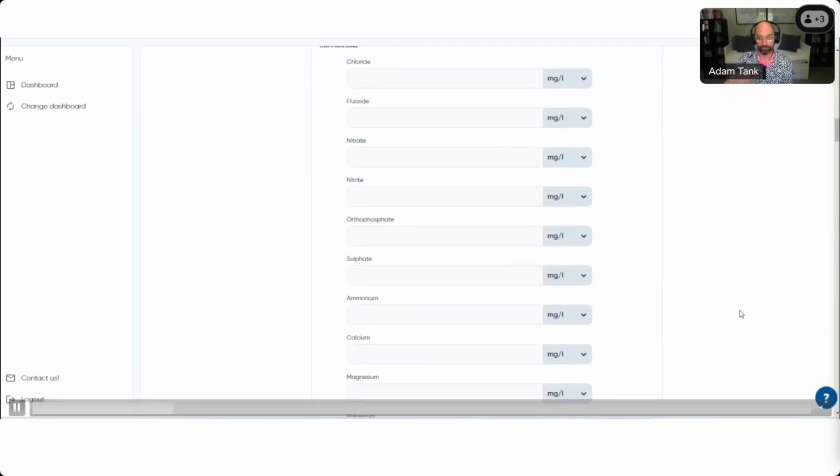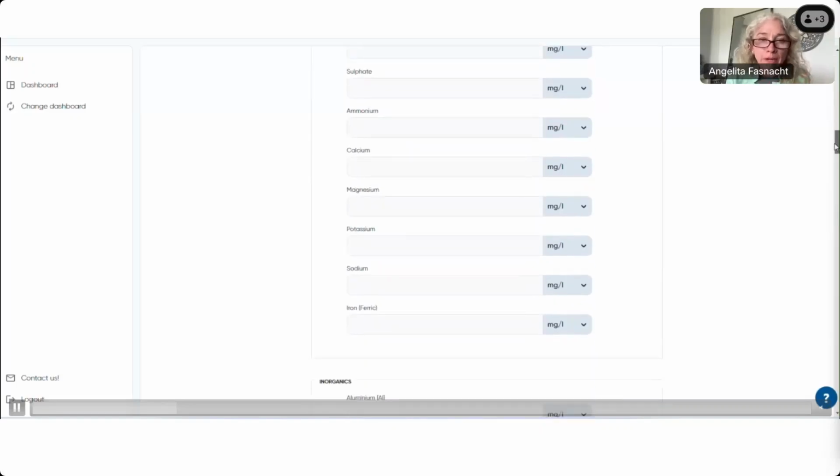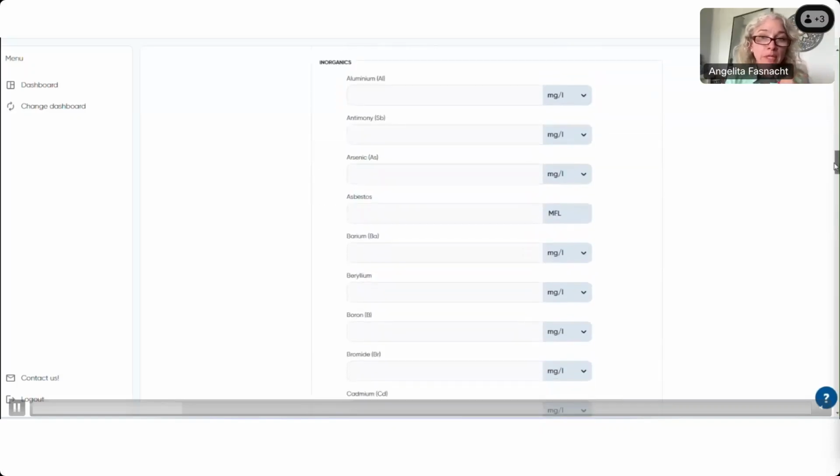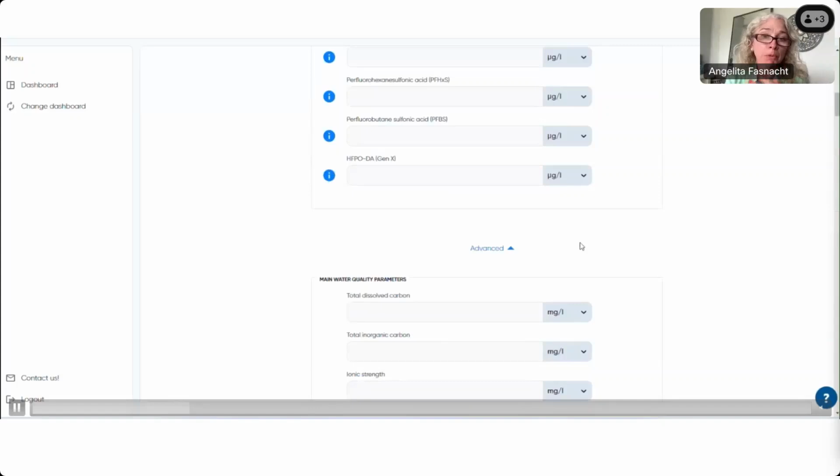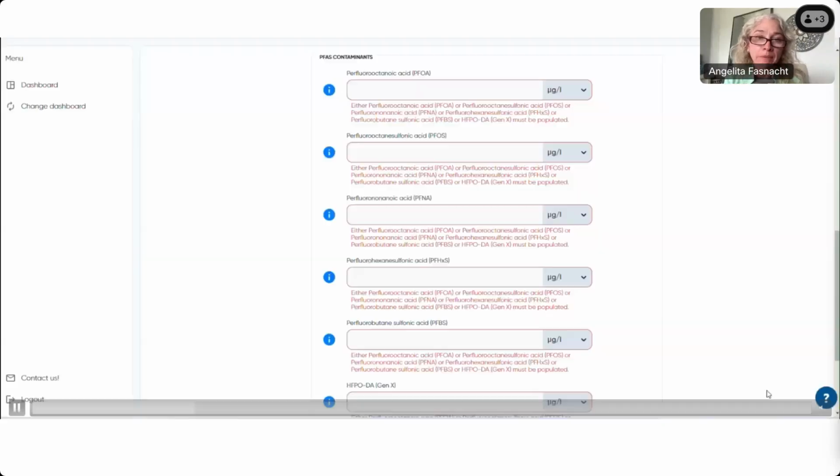Sure. So after setting your PFAS levels, you could set them based on what you want to remove. Do you want to set them up as a removal rate? Do you want them set up as a specific concentration target? That's a little bit more advanced, however way you want to do it. Then there are other types of parameters that are important to take on, like TOC, iron and manganese. This is important because they could compete with the adsorption process. And so knowing those, if you have that information, will be critical to be able to get a better design at the end.